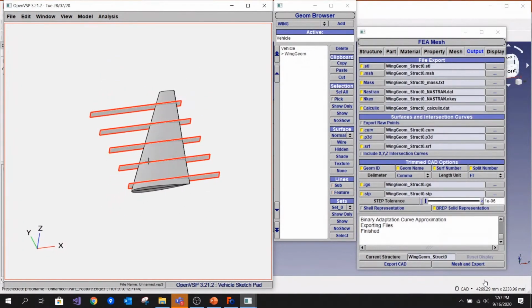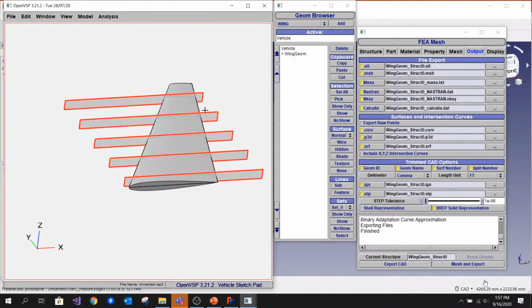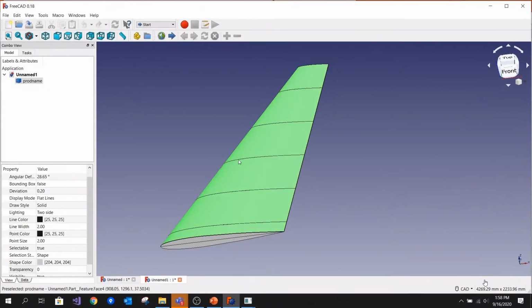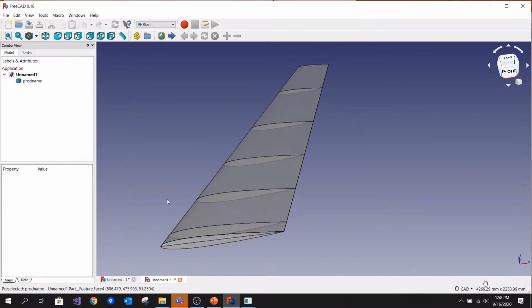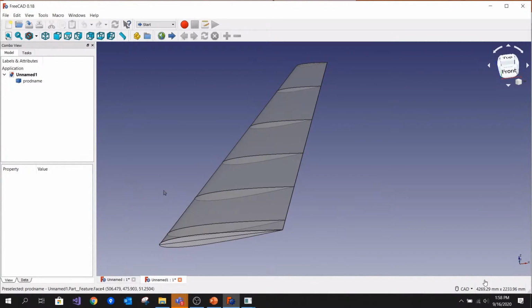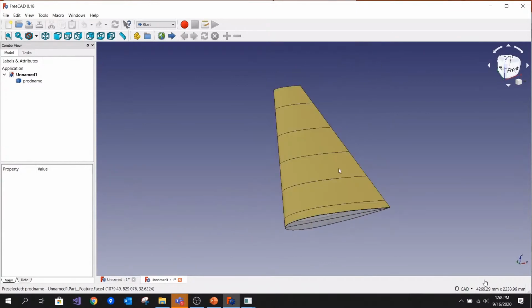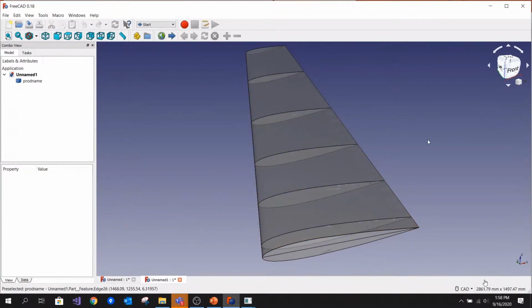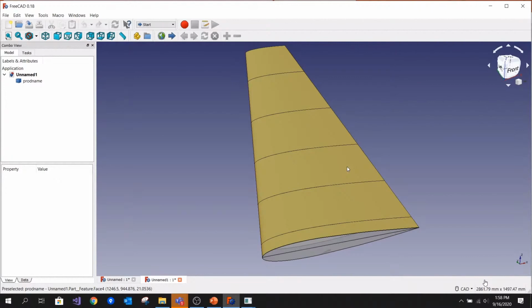we have these cutting planes that are much larger than the area that they're actually intersecting with. But all that's left behind when you export is the intersection curve and what is inside of the wing. So that's what that capability is there. Like I mentioned earlier, the wing itself is not broken into different surfaces at those intersections. So that's something that is a limitation right now. Just the ribs are trimmed against the OML. The wing itself is not involved in any of the trimming algorithms otherwise.